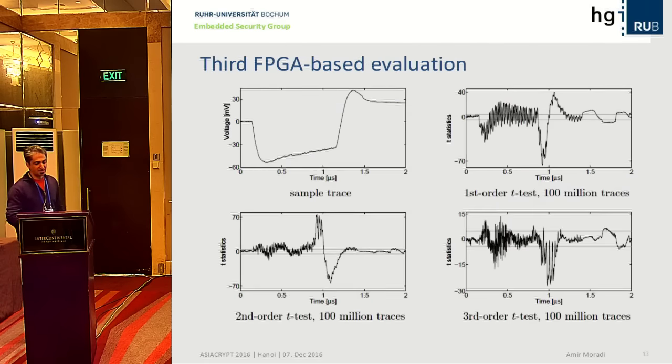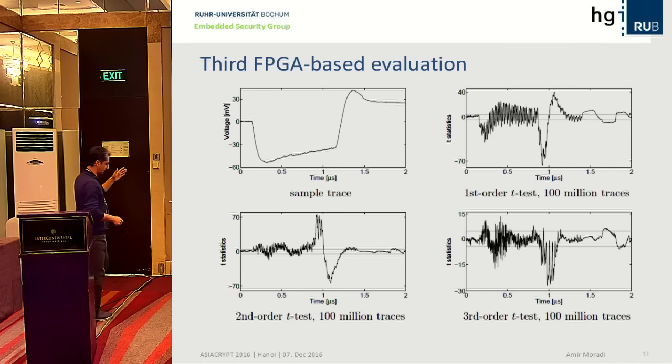But if you implement this on an FPGA, it was pretty hard, because asynchronous circuits are not made to be implemented in an FPGA, or let's say FPGAs are not designed or fabricated to realize asynchronous logic. Then you see here the small clocks. Actually, the clocks are internally generated by the system itself. This is the active signal for the registers.